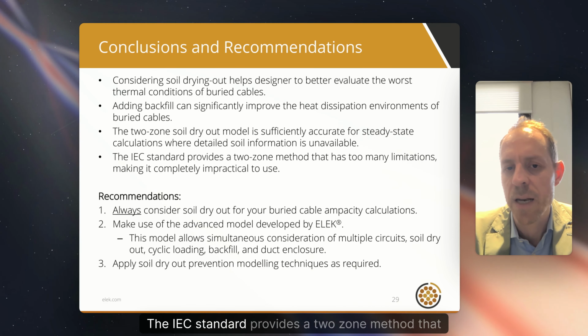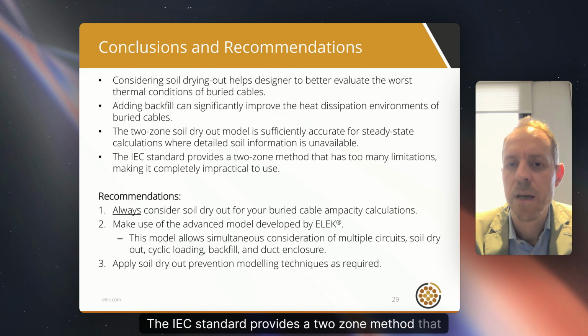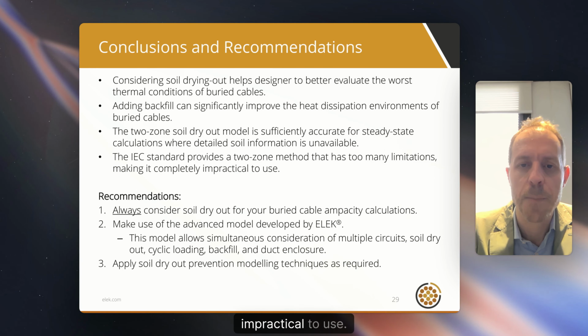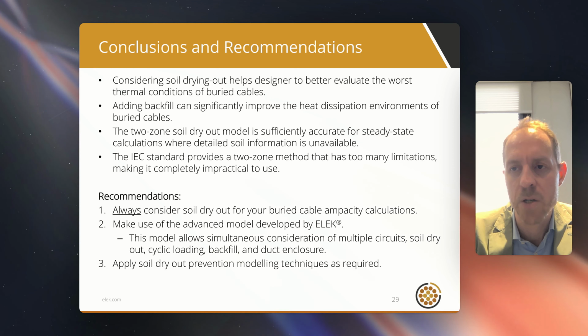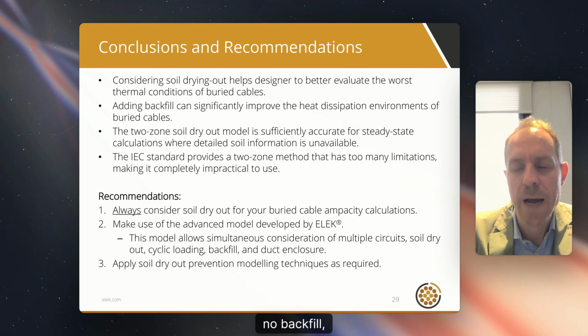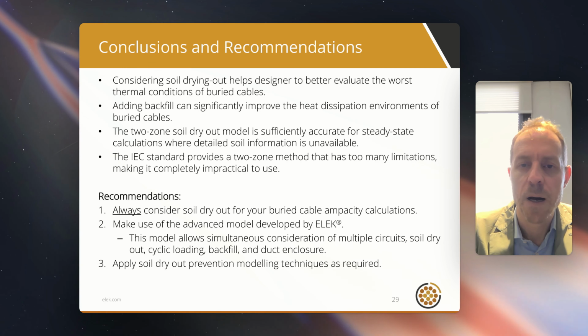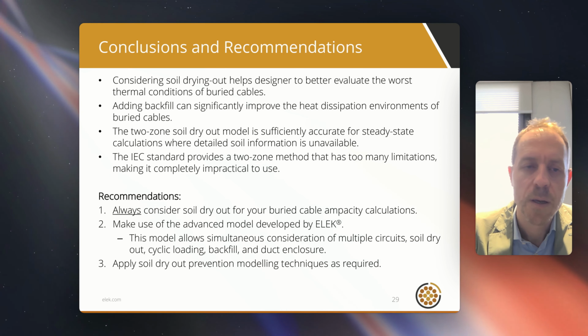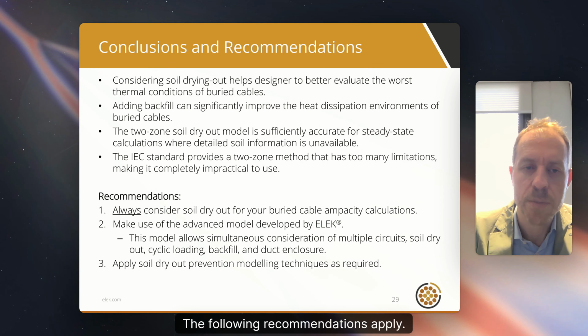The IEC standard provides a two-zone method that has too many limitations, making it completely impractical to use. You remember I mentioned those limitations: a single circuit, no backfill, no ducts, and a unity load factor only, no cyclic loading. The following recommendations apply.